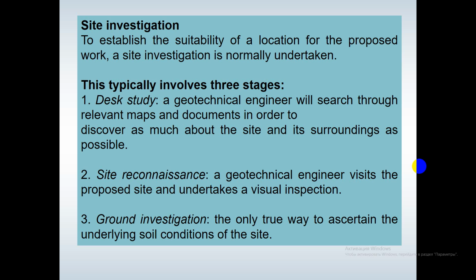For example, tree cover will be assessed as this can indicate soil type and saturation levels. Also, willow trees require very wet ground.